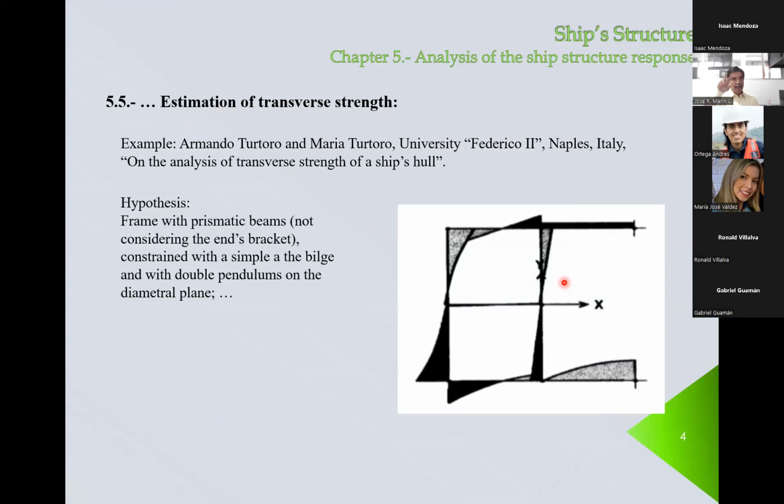Okay, so those are the assumptions, and these assumptions can be converted into boundary conditions, and we could develop this analysis. But remember that we have one beam here and another beam here, so they are different. Now, the deflection at this point is the same, but the deflection is in the Y and in the Z direction. So we have to be more careful with the analysis. That's why it takes longer time, but we don't have the time to explain how we can solve this.